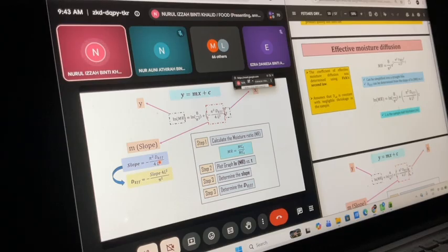You have to remember that the L is actually only half. Even though the thickness is, for example, 10 cm, your L is only half, so 5 cm. This is a common mistake that students make in the final exam: they know that the thickness is 10 cm, for example, and they do not change the L value. L is actually only half.